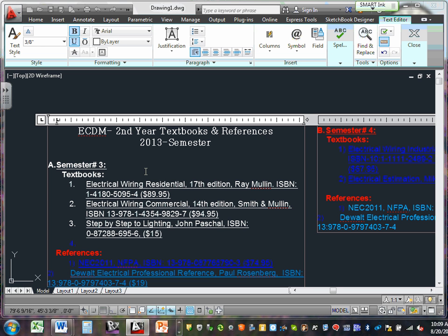Now you probably don't know what by layer is. Later on it's a big deal. It means every time you pick that particular layer, this text will come exactly as you want it to come. When it comes to CAD, guys, we like to work by layer. I'm going to open the topic of layers tomorrow, not today, because it's a good topic to open.